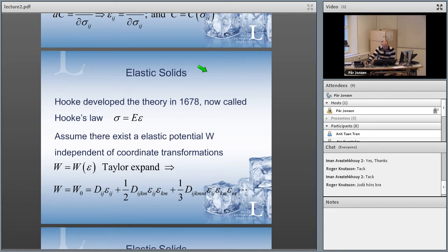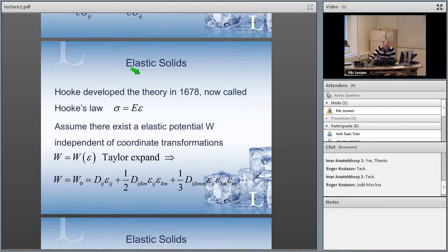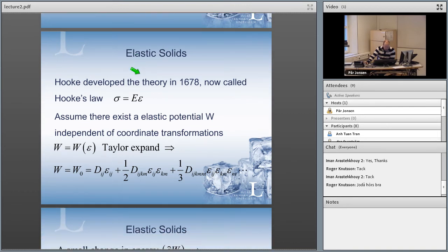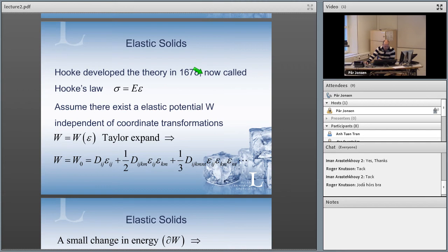And then you have a system like this. You take a Taylor expansion of that one. You will have an equation looking more or less like this. So you see here are the higher terms, and you have higher ranks of your tensors. So you can develop it as much as you want, but usually these nonlinear terms don't matter. And we know that we are working with small deformation, a small strain tensor in this case. So we can just use the first one.